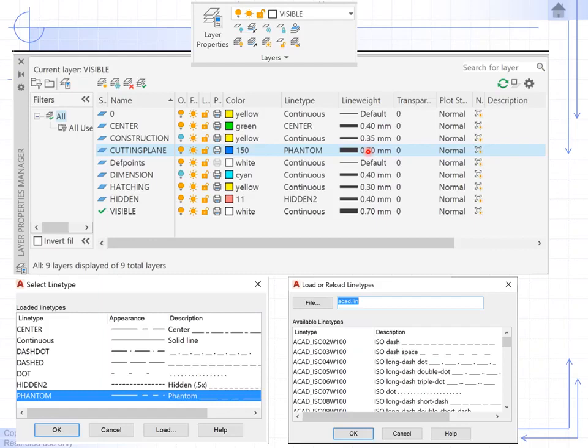You're also going to want to create a hatching layer. So you're going to pick a hatching pattern. So might as well create its own layer for hatching. So click on the create new layer icon, and it'll load it. Name it hatching. Click on the box to change the color. The line type you want to use is continuous, and you want to keep it at 0.30 millimeter in line weight and thickness, same as a center line or a hidden line.